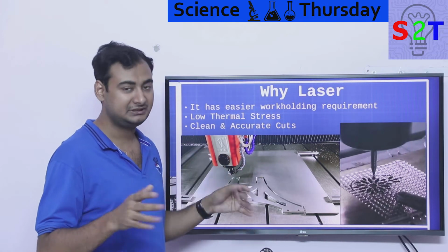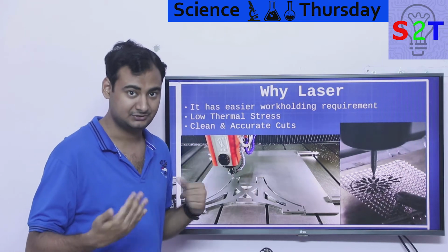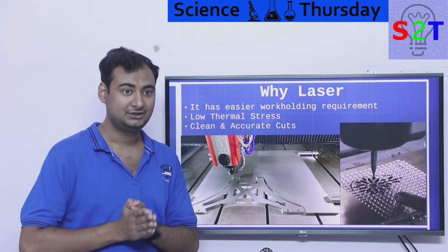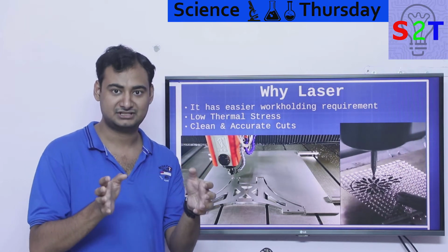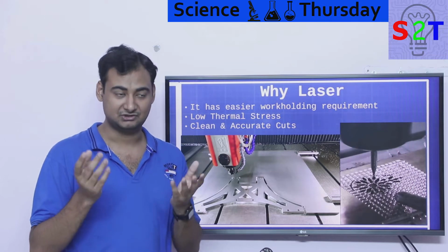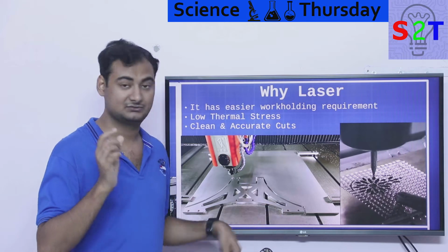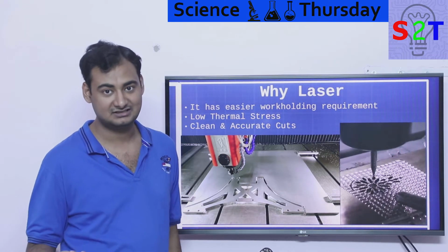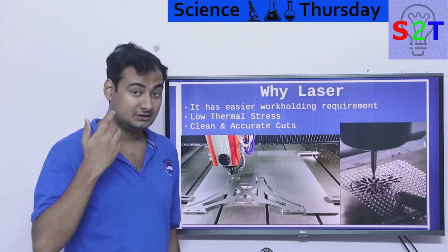And many materials will simply change their properties. Not only that, they will also change size, because in engineering, whenever you are talking about measurement, you also have to specify the temperature. Any experienced machinist will tell you, if you cut something, don't measure it right now, it will be hot, so wait a few minutes, because every measurement is temperature based, specifically with metals. If you say this metal is 1 inch thick, 1 inch thick at what temperature? Because if it's 1 inch thick at 30 degrees Celsius, it will be a different thickness at 20 degrees Celsius. So you have to consider that aspect.